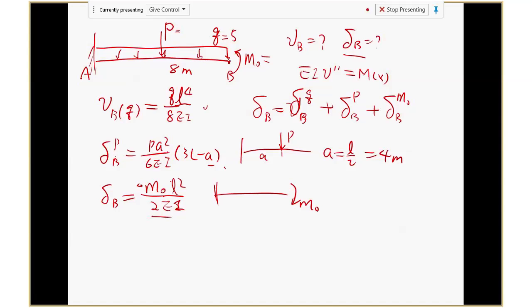Any questions about this example? Yeah. Don't B and delta have opposite senses? Whereas deflection is considered to be positive down, but delta is negative down. Yes. Okay. Here's a question. If you look at the table, they give you Vx. They also give you delta. But if you look at the Vx, you plug the x value, x equals L, what you get will be a negative value, because the V sign is pointing upward.